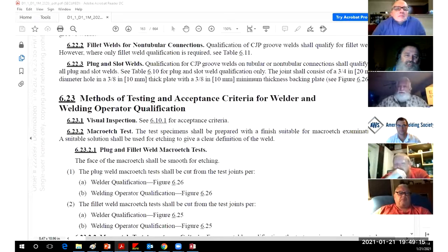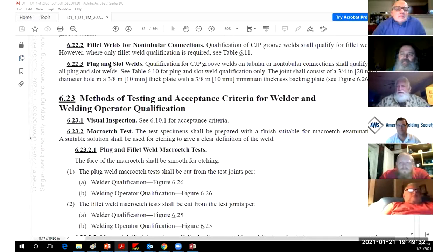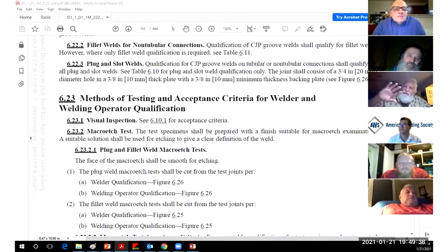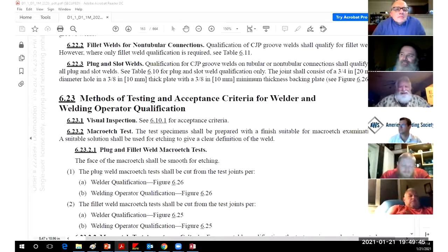He sat there the whole time, and I had to do a few of these columns because they took a core sample. They just drilled through the column, so they drilled through the structural reinforcement, which is rebar. So I had to do a procedure just like that. That was one of the toughest tests I ever had to do as a welder. When they came back, I had to grind the face of the rebar down. He took his little machine and went through there and tested everything.